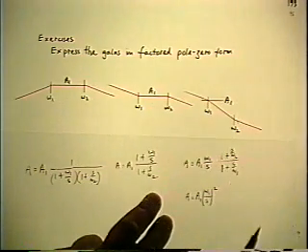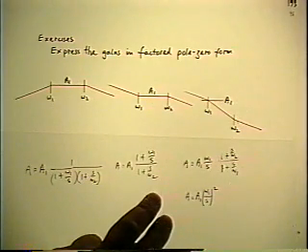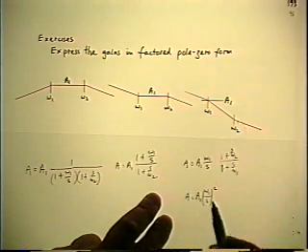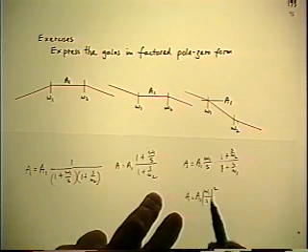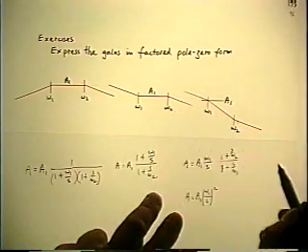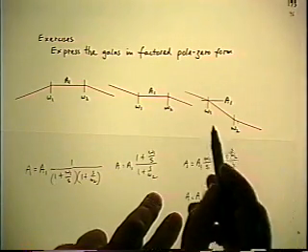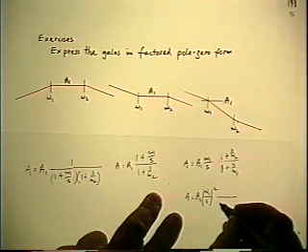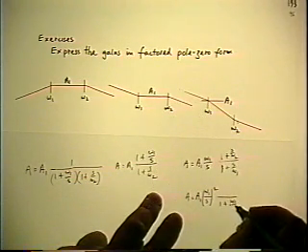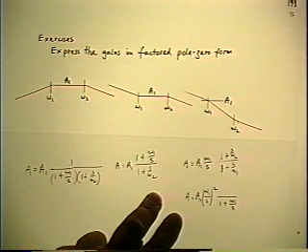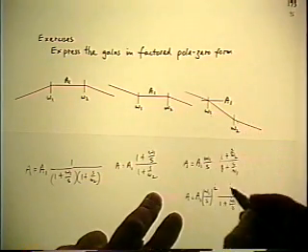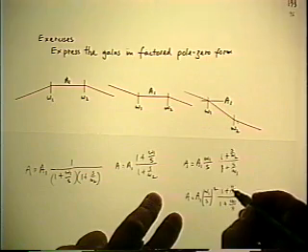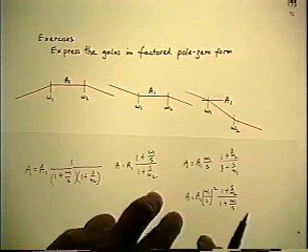Remember, it's double log scales. Now the middle asymptote has been adopted as reference, so now you look both down and up and see what happens, and when you look down you see a concave downwards corner, which is a pole, but it's an inverted pole at omega 1, and when you look up you see again a normal zero at omega 2.